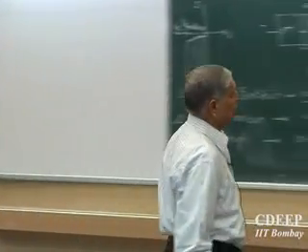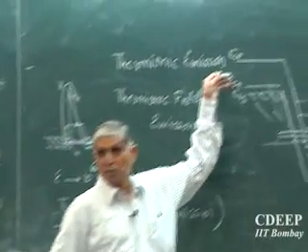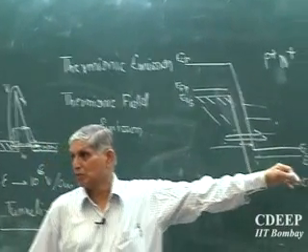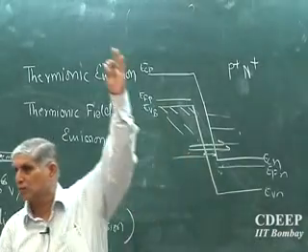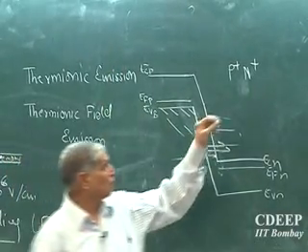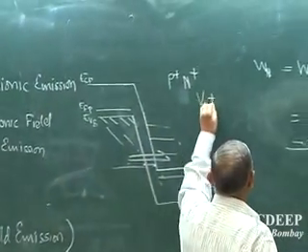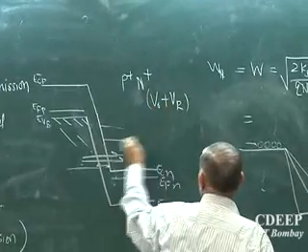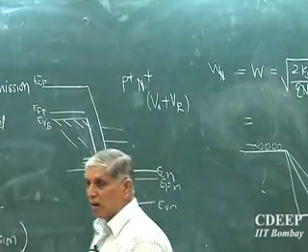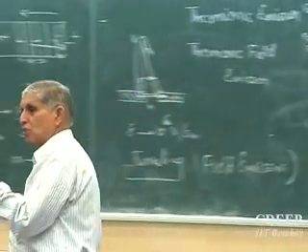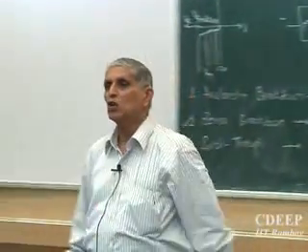If you apply reverse bias, that means the Fermi energy in P is larger than the Fermi energy on the N side. That's a reverse bias. So if I apply V0 plus VR now, and the dopings are very large, what will the depletion width be? Larger doping means depletion widths are smaller or larger?